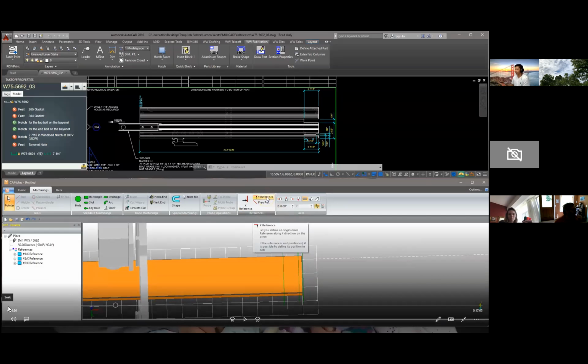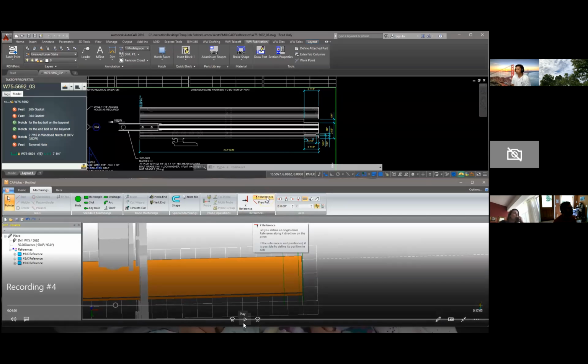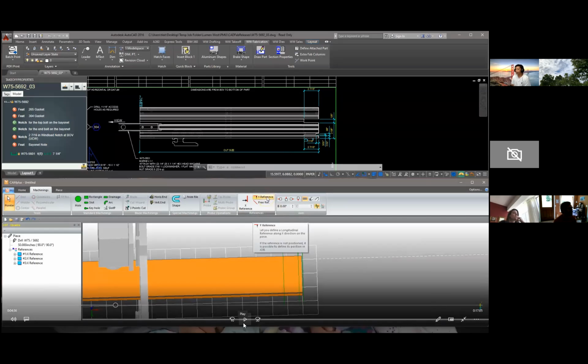And why is it 1/8? Because most of our blades are about 0.2 inches wide. Let's say the width of the blade is 0.2 diameter. So the 0.18 encounters the separation cut. When we are cutting the part, the separation cut is making the pieces into the correct cut size, so we can counter for it there. So we always add 1/8 on every single notch at each end.